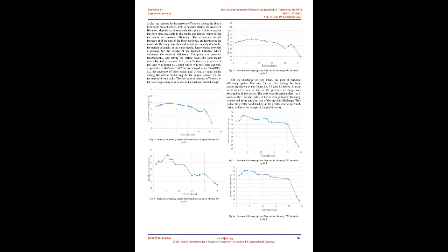When the water strikes the baffles, a mixing effect is created which increases the chance of particle collisions and hence, facilitates the aggregation. Also, it holds the bigger flocs in suspension which allows them to grow even bigger. The flocculator is designed for 10-minute detention time.